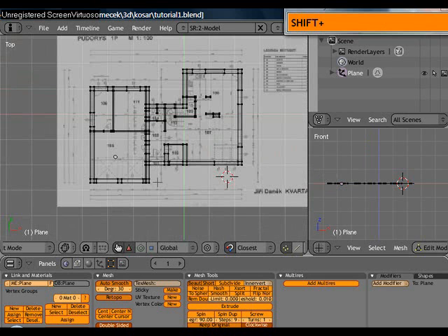Now I will extrude to the height of the apron, which I know from the blueprint is 1 meter high, but I don't know how to tell Blender to go 1 meter up, because my model is not scaled exactly. It was just done by tracing the background image that was not in any particular scale.